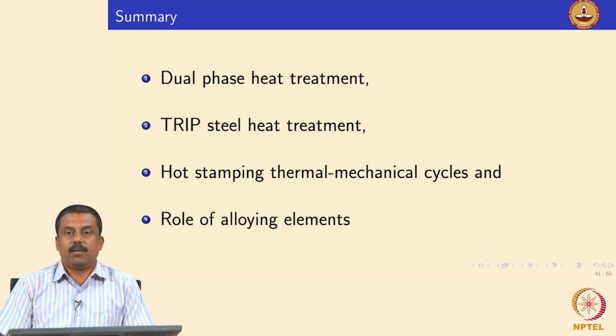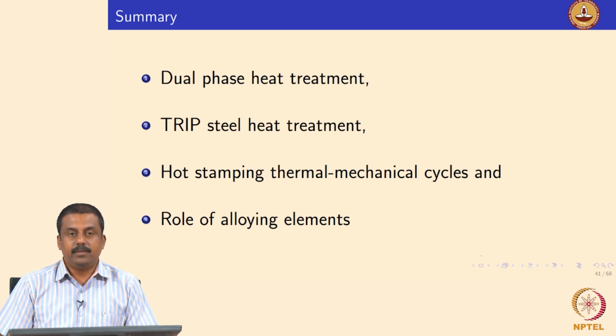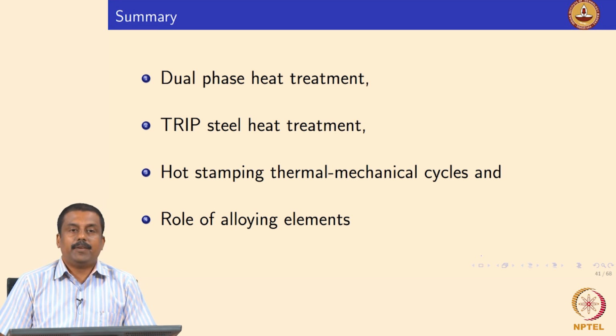when the austenite carbon concentration reaches critical values known as T0 or the paraequilibrium phase boundary. This boundary is defined by the carbon concentration at a given temperature where the Gibbs energies of ferrite and austenite become equal, and at this concentration the austenite can only transform to any other phase in a diffusionless manner. Therefore, it has to transform to martensite.